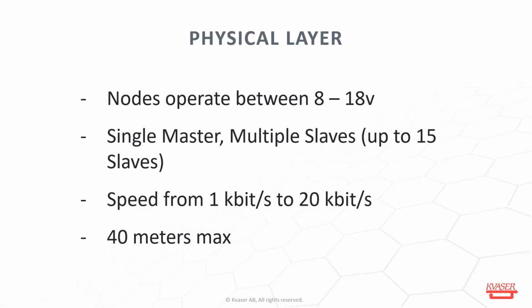So let's say you have a smaller system that works the turn signal. Just something simple like a turn signal. One node will say if it's turning right, one node will say if it's turning left. It'll communicate what's going on that LIN cluster up to the CAN bus so that a larger computer system can tell what's going on, possibly do something from there. That's just some of the possibilities that you have with LIN.